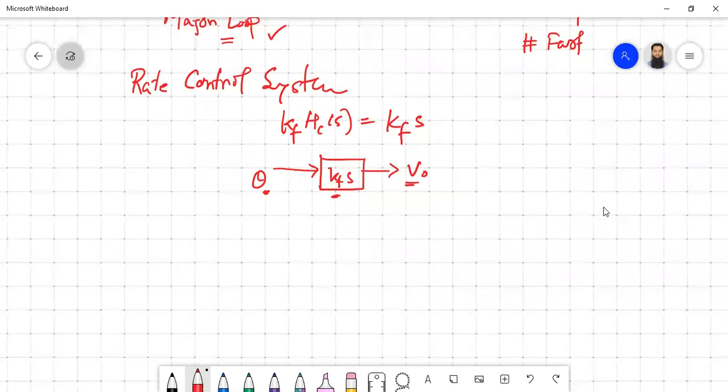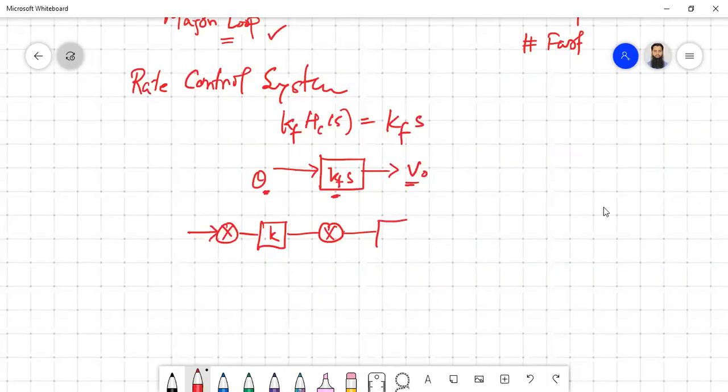So how does the actual system look? The actual system example is something like this. Now you have the gain K here. For the motor position control system, if you were to take the feedback as a rate feedback, this is your K1, then you have the plant, maybe the motor, G1(s). In this case, you don't have G2(s). G2(s) is in most cases an amplifying factor. If your plant needs additional voltage or power, then we do the amplification. So this is your rate control system.